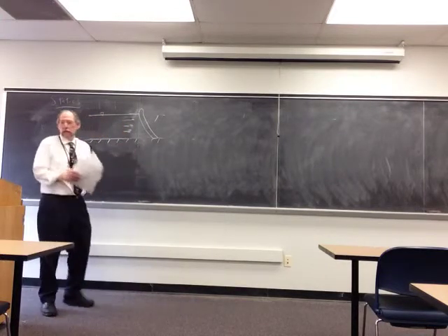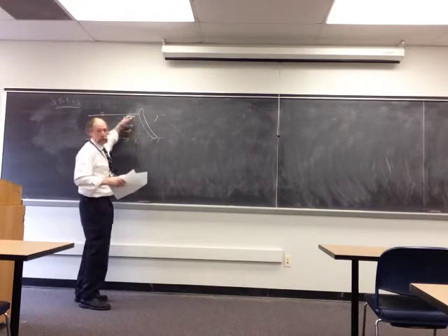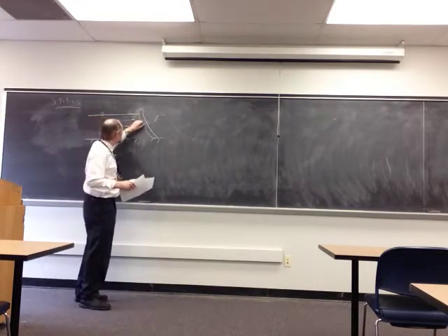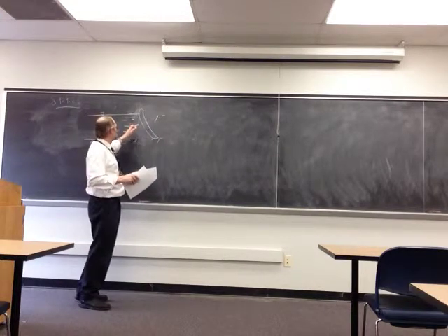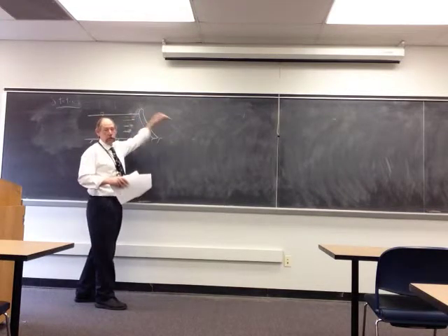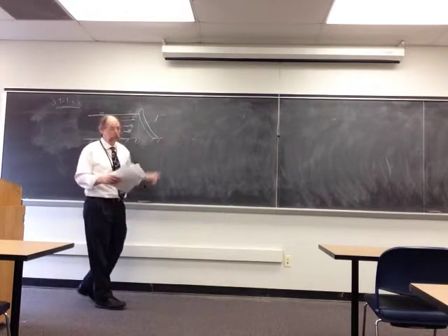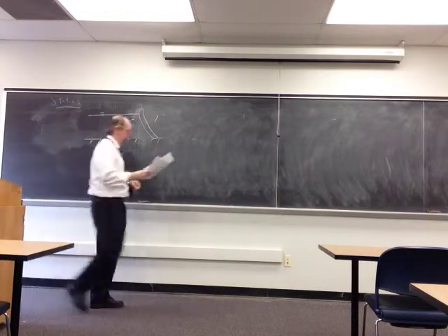But in all of these cases, knowing the center of gravity is important, because that's where all of this hydrostatic water force acts, essentially on that center of gravity. And you want to make sure that a force acting on that center of gravity is not going to push your dam over or push it out of the way. So you need to know where that center of gravity is.